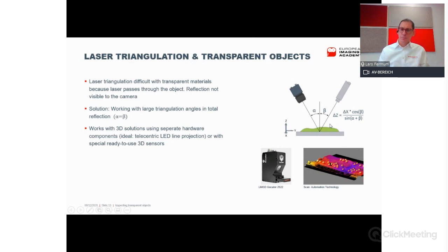The solution is possible with individual components, and in this case I would maybe use a telecentric LED line projection, or also special ready-to-use 3D sensors, like especially the LMI 3D profiler 2512, or the LMI 2522. So these are special models, as you can see here. It's not just the standard way of projecting the laser line.